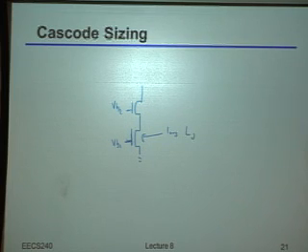How about the V star of that device? What did we say we wanted there, particularly from a noise standpoint? Well, you said we wanted the bottom to be higher than the top. That is going to turn out to be correct, although here it's really the current source relative to the GM that matters.